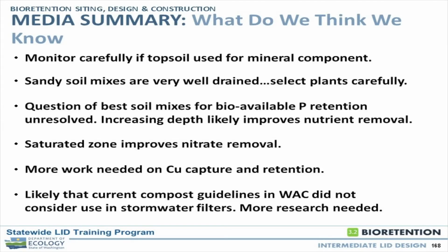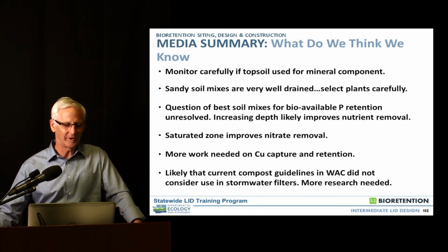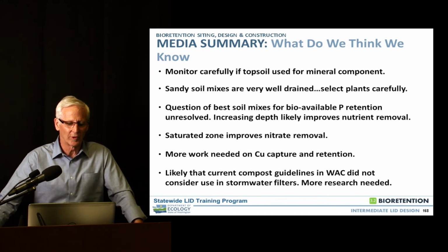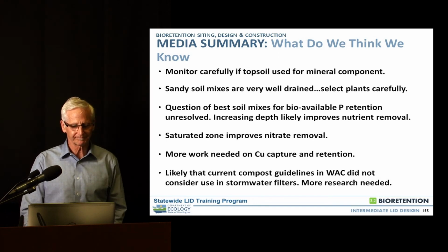If you're going to use topsoil, and this is really going away, I don't know if anyone is still using topsoil in Western Washington. If it is happening, it's very few. If you are going to do that, and you won't be doing this for bioretention areas, that's not going to fit the current prescriptions. For a rain garden, yes. But for bioretention, you're going to be using a more designed media. But in the cases where it might be used, you need to monitor it very carefully.